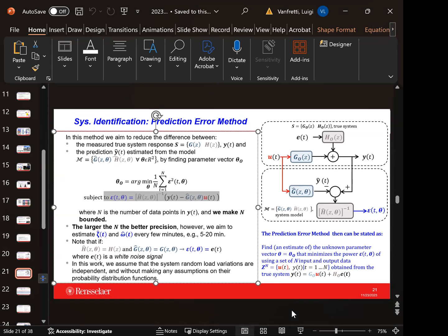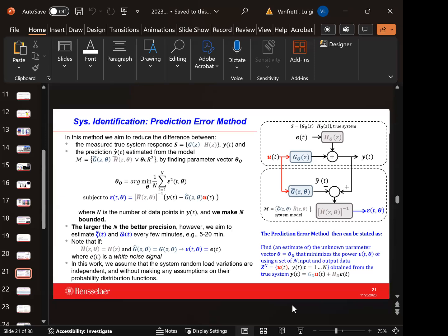Well, just for the ARMAX, of course, all the poles of the system are fixed, and you will excite at different locations and measure at different locations, so normally the transfer function between any points will contain these poles. In fact, it's a big closed loop, and when you excite a closed loop from one point to the other, any closed loop transfer function contains the same poles. Of course, in a network, you don't see all the poles so well; there are some unobservable poles.